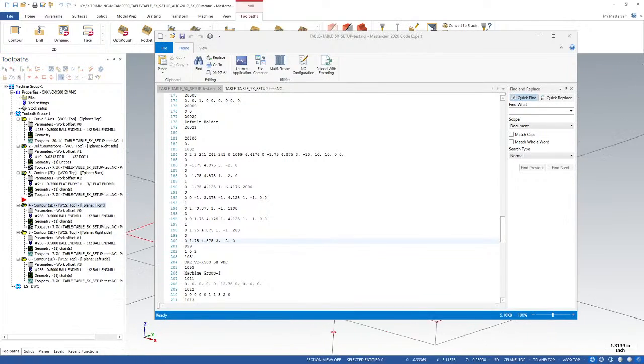It can be as complex or as simple as you want to get, but we need to be able to cause rotation on the machine to occur while we're in the middle of a cut. And that's what makes a toolpath a live vector-based 5-axis toolpath rather than a 2D, or we could think of as 2.5D tool plane based toolpath.